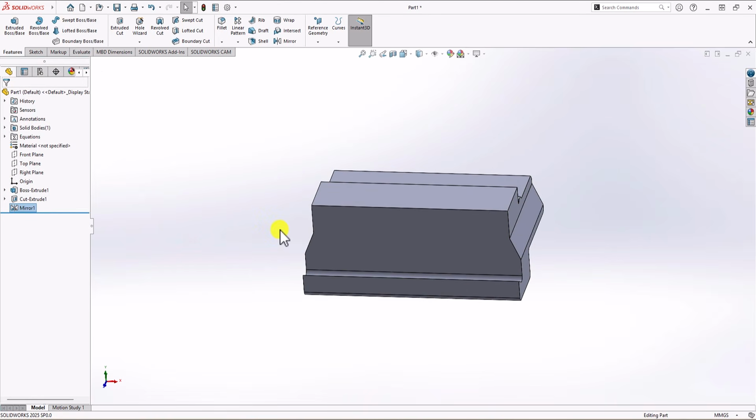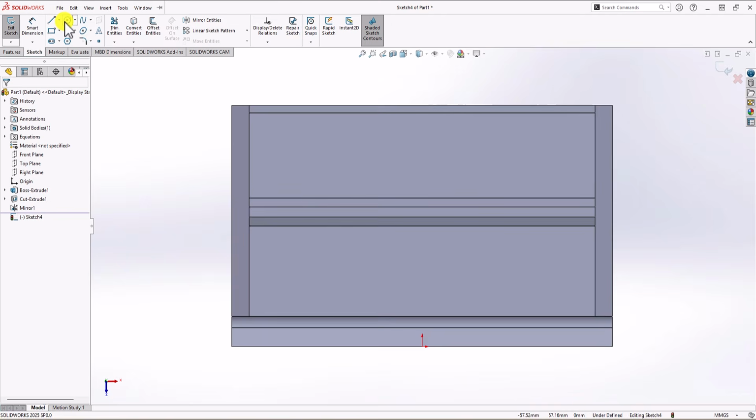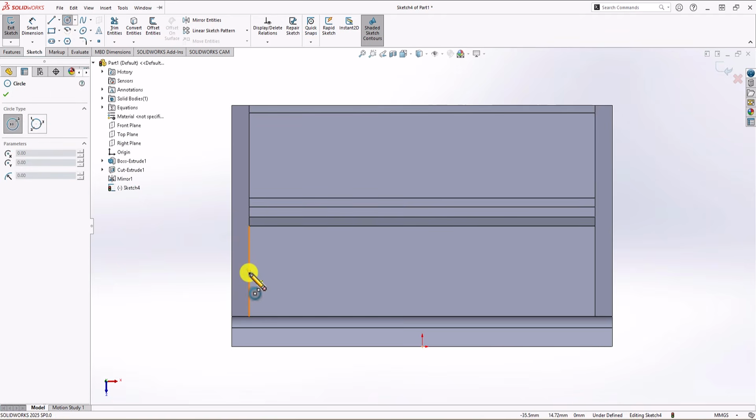Last step is to make 3 holes on the top surface. Click on the sketch command, and choose top surface. Here, there's no hint in the question about the location of the holes with respect to the y-axis. But again, it doesn't matter, because at the end of the day, you want to make a hole and you want to find the total volume. So as long as you have the size of the hole perfectly, then you're not having any issue. So for now, I assume that the hole is in line with the center point here.